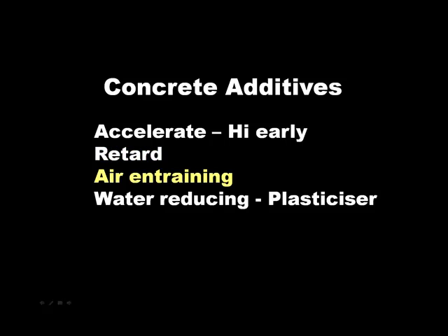Air entraining, I mentioned briefly. You can control the amount of air by introducing additives. There may be enough air resulting from the natural materials that you're using, but you may also want to introduce an air entraining agent.